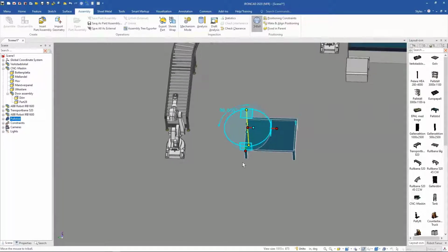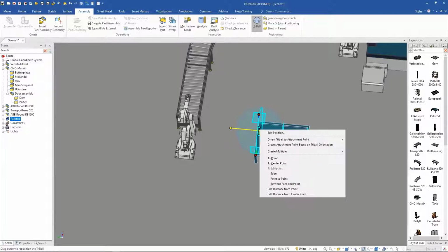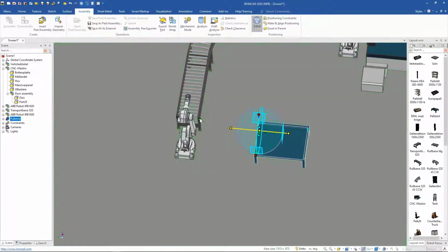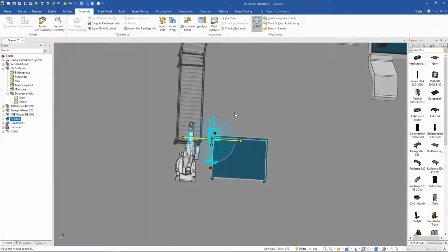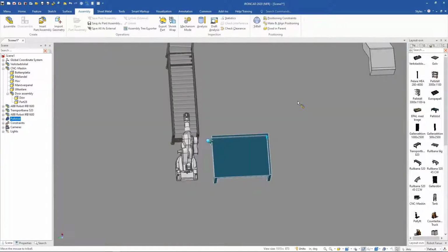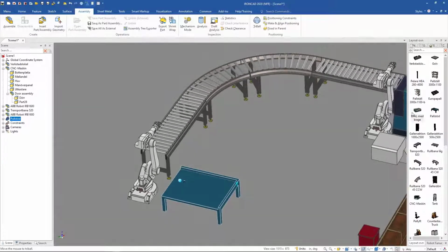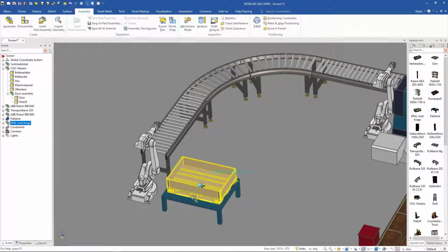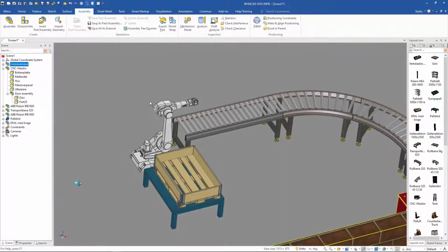And I actually want to locate this corner right off this corner, so I can say, okay, move this. I want this to be a set distance from this side right here. And 12 inches is good. That's perfect. And while I'm setting it there, one of the things that I really want to be careful about as well is that the robot can reach all the different areas. So this is a time where I do want to check how well I've done. So let me just pop in this and notice what's happening. As soon as I pop that, it moves into position because it has an attachment point. So now I want to be able to make sure that what I've done here is going to work.